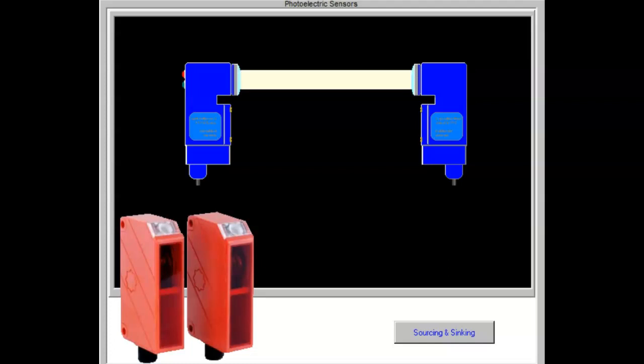Direct scan requires that the light source and the photoreceiver are positioned opposite from one another so that the light source shines directly at the photoreceiver. The object to be detected passes between the light source and the receiver. If the object is opaque, the direct scan will yield the highest signal ratio and is normally the best choice for the application. As long as an object blocks enough of the light, it may be tipped or skewed in virtually any manner. A general rule of thumb is that the object size should be at least 50% of the diameter of the photoreceiver lens.